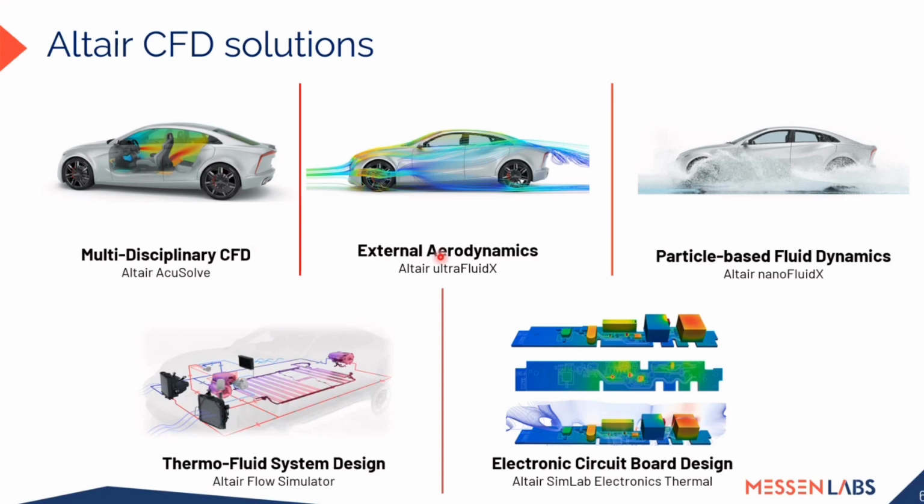Then we have UltraFluidX, which is specifically designed for the external aerodynamic case. From the design point of view for ground vehicles, aerodynamic coefficients play a critical part in the design. So we have a special solver, UltraFluidX, which is built for the same. It is based on the LBM method and it is a GPU optimized solver, so it is extremely fast and efficient.